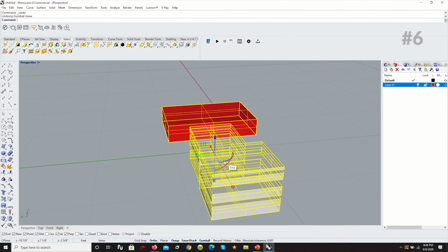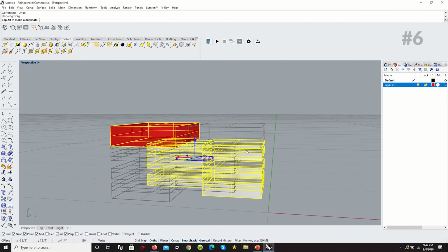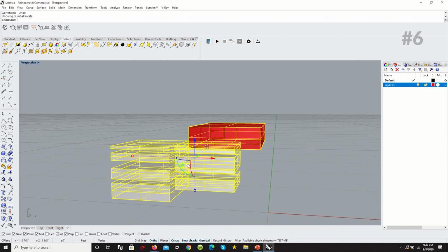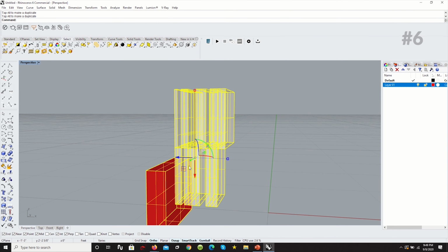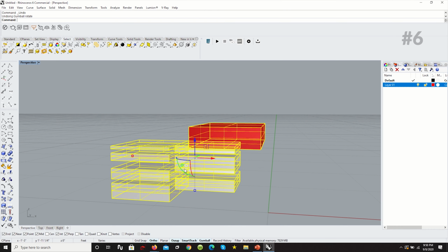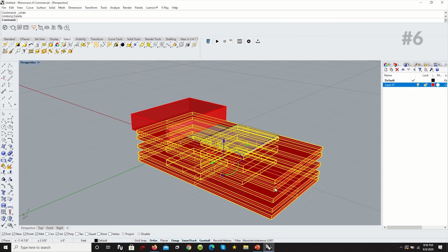It also makes for a good rotating tool. So you could go here, you can just select the blue area and begin to turn it along this axis, turn it along that axis, or even turn it along this axis. It's another fast and simple tool that you can use aside from using rotate 3D or the 2D rotate command. So let's undo all of this.